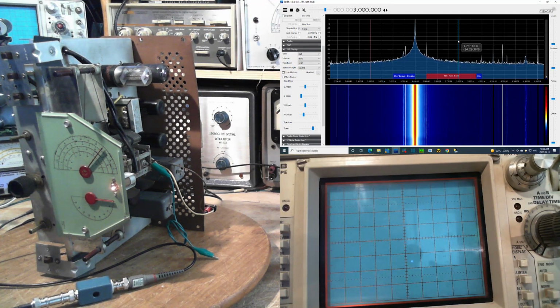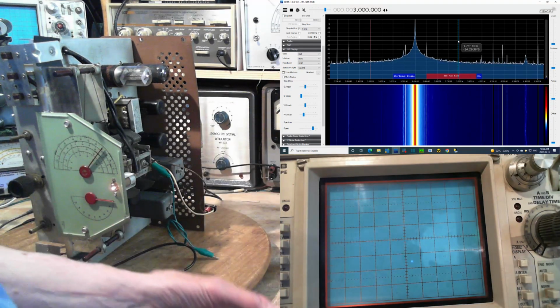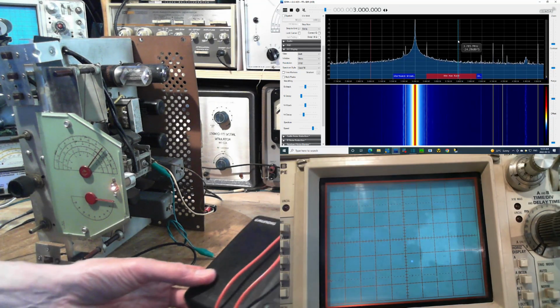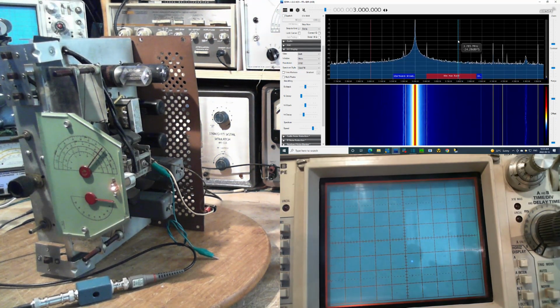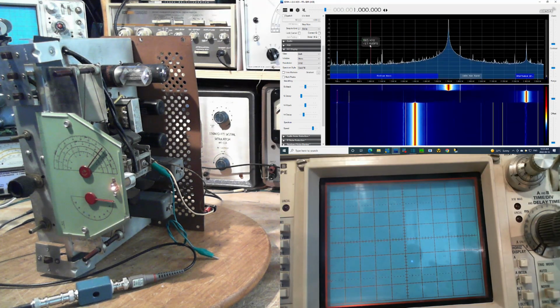See, what goes on in the back of my mind here in these radios is that the converter tube isn't just converting the incoming desired antenna signal and the local oscillator working together, and that's all that's happening. No, there's a whole pile of signals, and they're all getting converted into new signals, or there's new products coming out. And then some of those products, could they get kind of re-involved again? Is that possible, that you get products of the products? That's kind of what I'm trying to search for here. It certainly does prove that there's piles of signals in these radios. Piles and piles of signals.